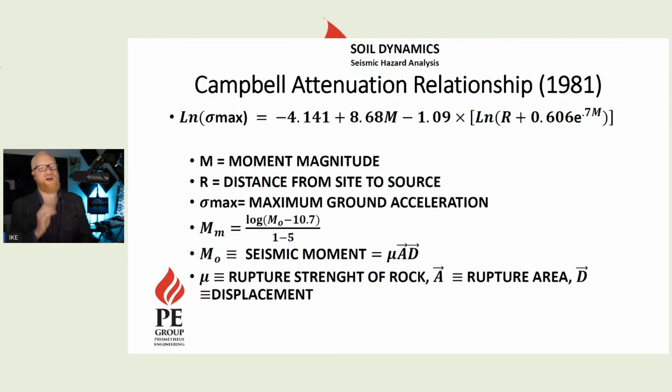So we plot for different periods this spectral response, which is the response of the structure from the ground motion. Now, I keep repeating this because it is very important verbiage for structural engineers, and engineers generally, to understand how the soil dynamics goes into the structural dynamics in terms of how we model it and what that map actually means. What the spectral acceleration means, because a lot of people seem to think that the spectral acceleration that is mapped is actually the acceleration of the floor. No, it is the acceleration of a single degree of freedom model with a particular period. So the map will tell you the period, in other words, period being the inverse of frequency, the natural period of the structure. The map will tell you this is for a period of 0.2 seconds, 1 second, and so forth.